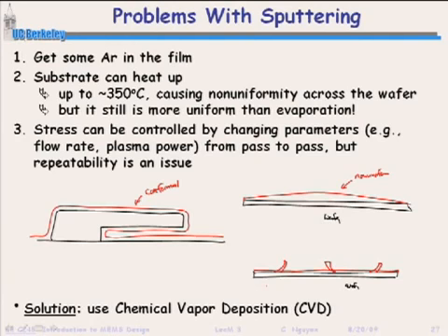That's why I told you, when I started my company, and we were trying to use a CMOS foundry as a foundry, it took a long time for them to learn how to do it. Because they were great at depositing films, very pure films and that sort, but they weren't great at depositing films that didn't curl up after they were released. And you have to teach someone how to do that. It takes time to understand that. You're going to learn that in this class.